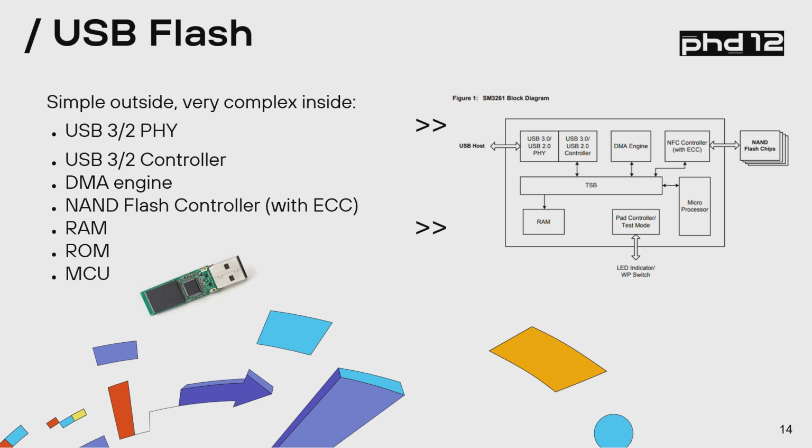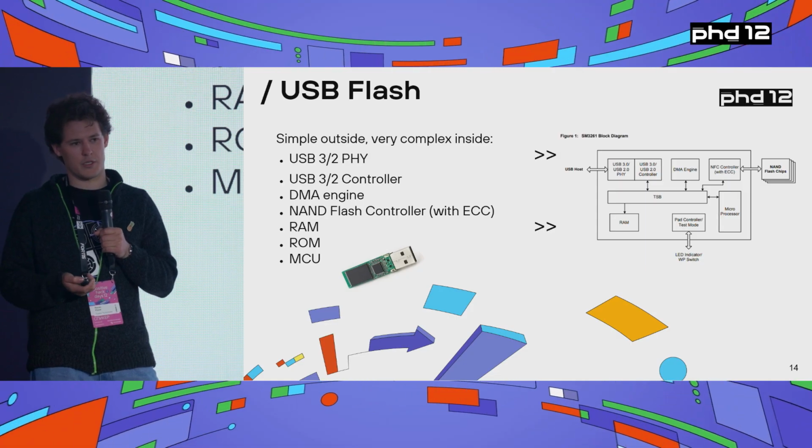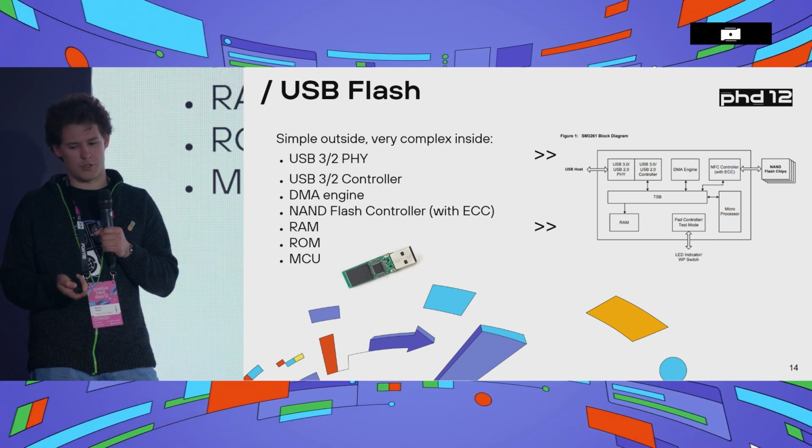So as a software developer, you may discover you're not dealing with data at all. You will be too busy setting up various controllers with your bits. In all probability, you will find it very difficult to spoof or replace data as such there. So if you decide you want to spoof the data there, you will need to play with the DMA controller and learn what kind of arguments it's using.